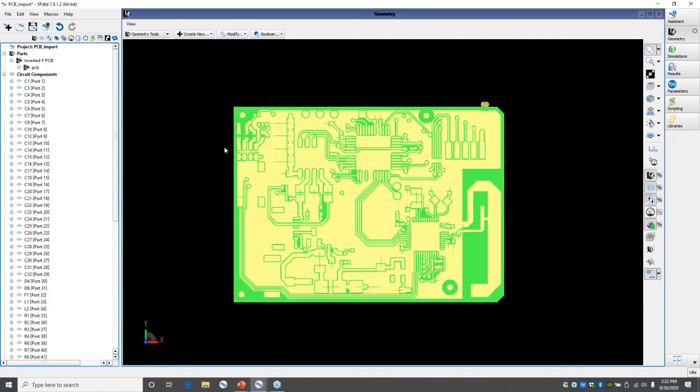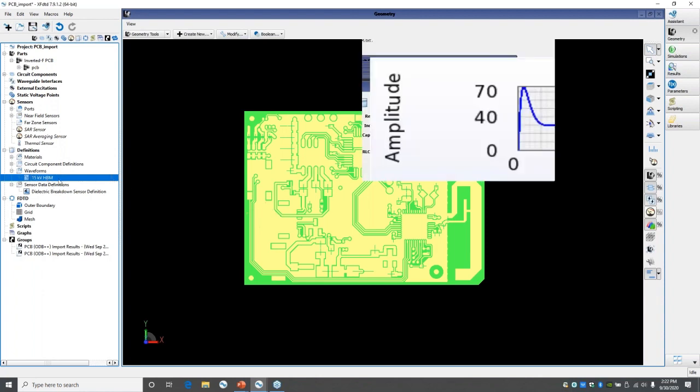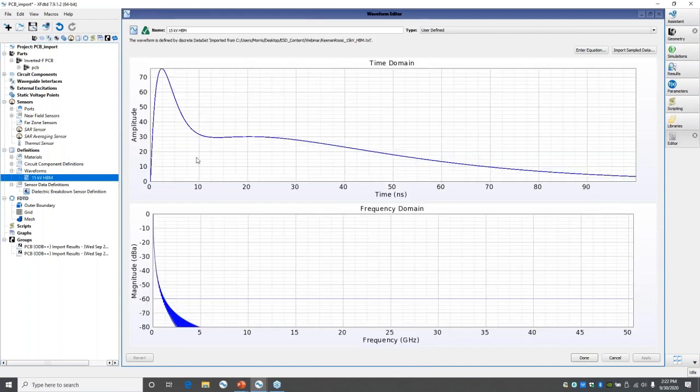So the next feature that I would like to show you is the capability to sample the dielectric breakdown data. In most of the ESD simulations, we would be using a human body model waveform, which is similar to the one that I have on the screen, which is a double exponential function. In these kinds of tests, it's usually possible that we see ESD breakdowns at the peak of the waveforms. So it would not really be useful for us to monitor the breakdown happening in the first half, or until the waveform reaches the peak.